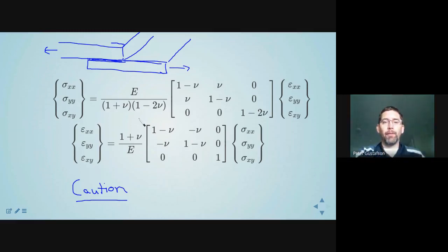Okay, not seeing any more questions. Oh, here's one more. So Nicole asks, so plane strain is if something is thick in one direction, and plane stress is if something is thin in one direction. So as a very simplistic statement, I would say that is generally true. Not always true. You've got to be careful, but as a general, elementary description of when to use those, yeah.